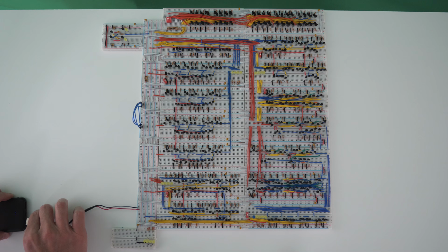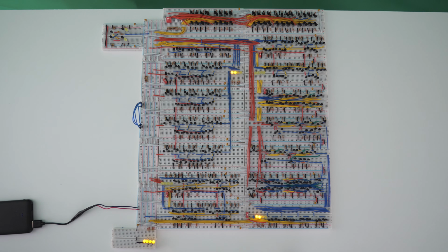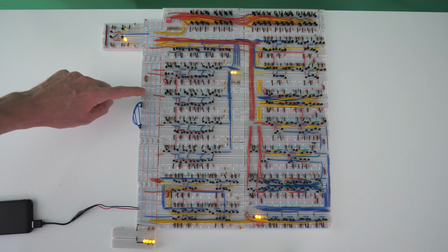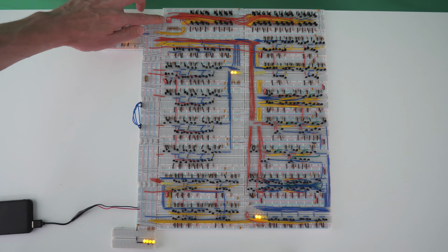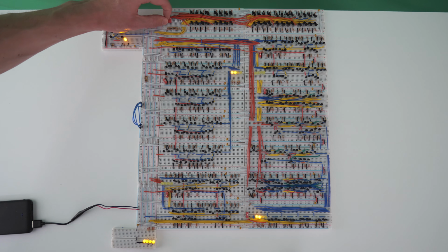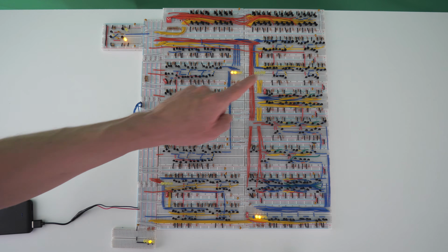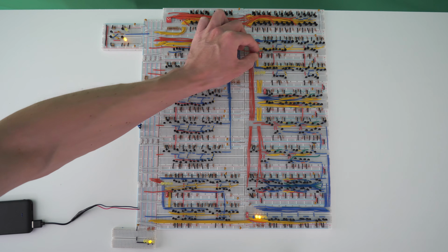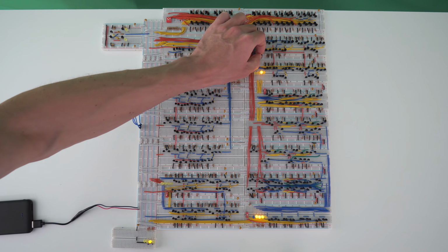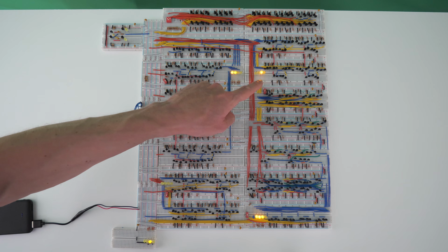All right, I'm going to power up this computer, and I'm going to make it so that it increments by 2. In order to do that, the first thing we need to do is have the value of 2 be sent from memory to the data bus. I know that the value of 2 is actually in the second memory location. So I'll flip this switch. We have a 2 on the data bus. We need to send that to the B register, which we can do by flipping the switch right here. So now we have a 2 in the B register.